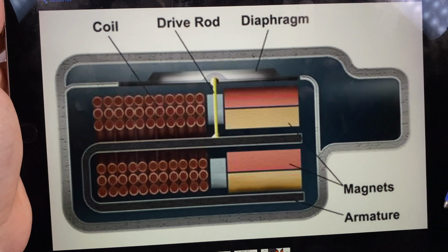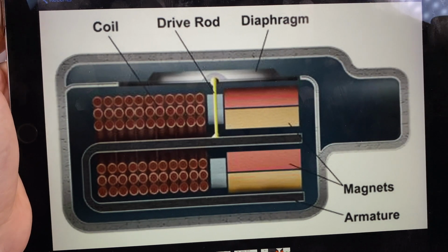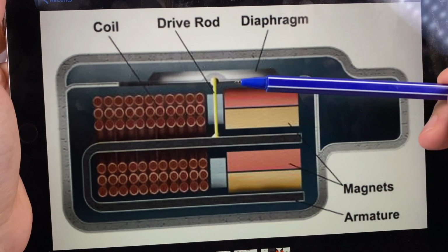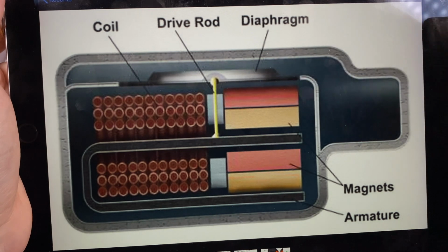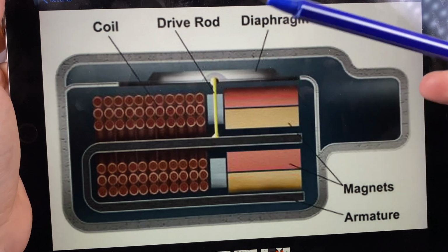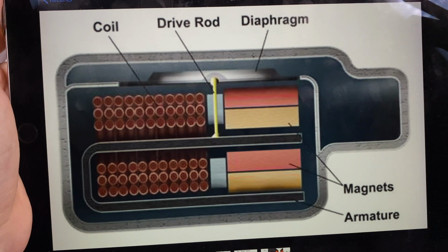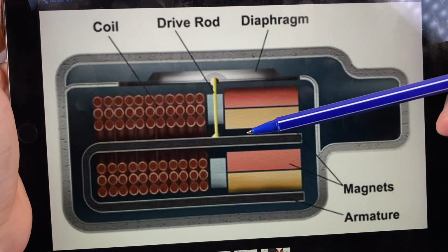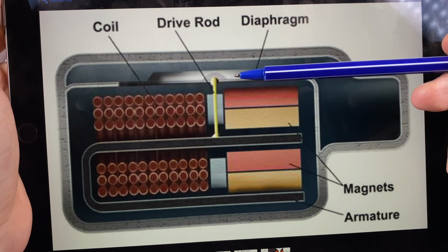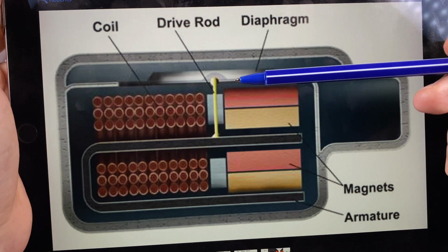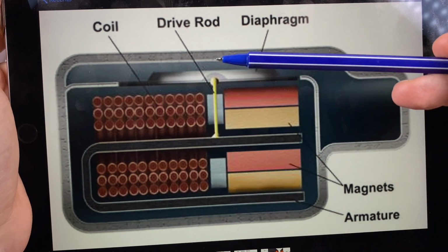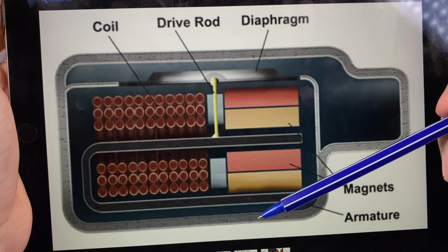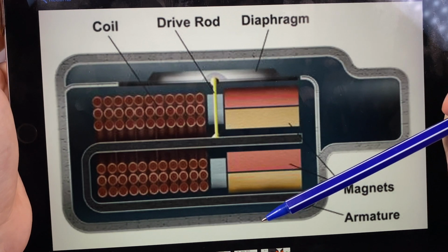And another problem with balanced armatures is that they usually don't cover the whole sonic spectrum. There are balanced armatures for high frequencies, for low frequencies, for mids. So you know what I want to say, and often the solution for that is to combine a few different drivers, sometimes using some crossover to split the different sonic frequencies. So a few drivers for treble, a few drivers for mids, a few drivers for low frequencies.